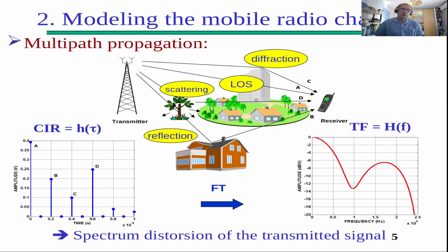When you look at the main physical effects on the mobile fading channel, the first one is the multipath propagation. When the transmitter transmits the digital signal to the receiver, the electromagnetic wave interacts with different objects that you find in the environment, and with phenomena like diffraction, scattering, and reflection, you've got the creation of several copies of this transmitted wave.